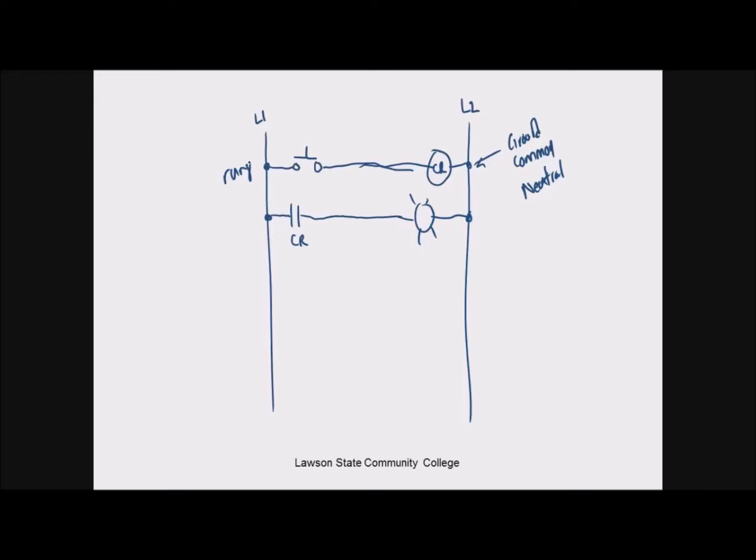Now there are basically four. One of them is called a function block diagram, which is more like a flow chart that you run into in computers. And then we have several other languages that are neat, and they do better code, but they're not what most people use. So this is the predominant language in PLCs, it's ladder. You'd have to be way up there before you moved over to those other languages. We don't have lights inside the PLC, and we'll look at that later on. So what we do in the PLC is we program using ladder logic. And that's what we're going to use in this class, ladder.